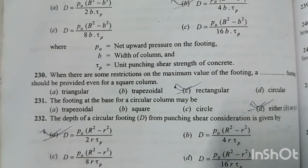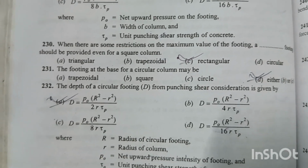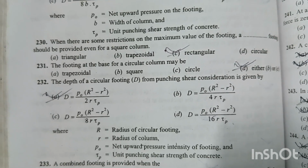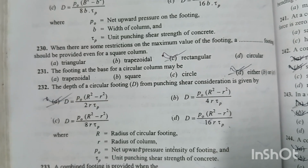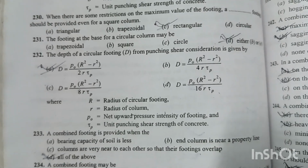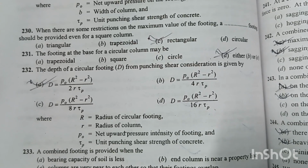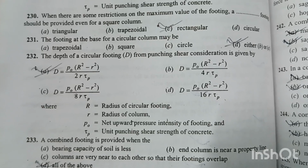Question number 232. The depth of circular footing capital D for punching shear consideration is given by. Option A is right answer. Capital D equal to P naught into root over capital R square minus small r square divided by 2r into tau p, where capital R is the radius of the circular footing, small r is the radius of the column, P naught is the net upward pressure intensity of the footing, and tau p is the unit punching shear strength of concrete.